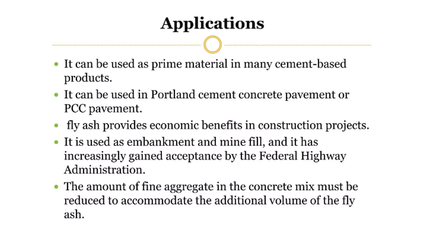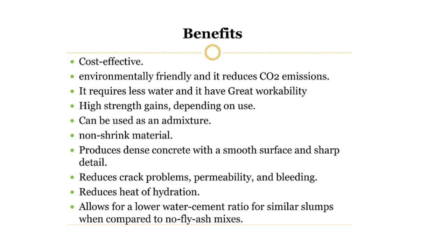Fly ash provides economic benefit in construction projects. It is used as an embankment and mine fill, and it has increasingly gained acceptance by the Federal Highway Administration. The amount of fine aggregate in the concrete mix must be reduced to accommodate the additional volume of the fly ash. Some of the benefits of fly ash: cost effective, environmentally friendly, and reduces CO2 emissions.